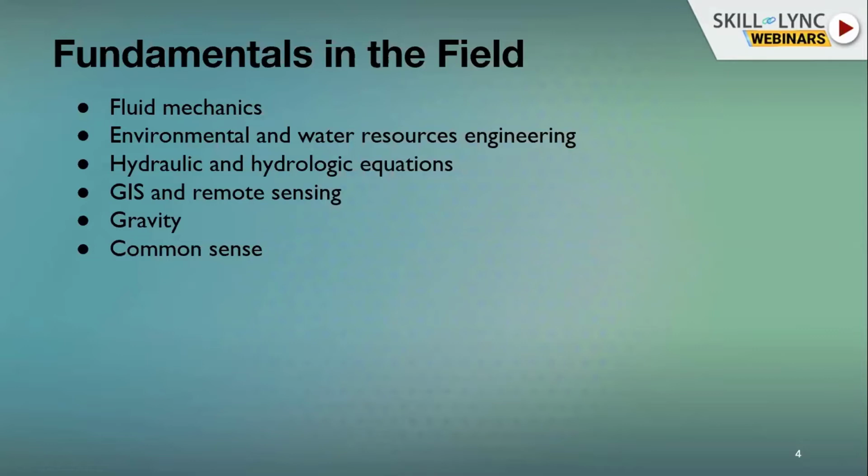I would recommend that people have a good knowledge of these equations, which are developed using the continuity equation. People should really understand what happens when, for example, Q = AV and my V gets reduced. What will it affect in my cross-sectional area or my floodplain? People should have a good understanding of these hydraulic equations.